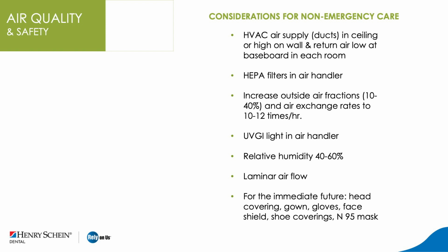We also want to have a relative humidity established in our office somewhere between 40 and 60%. I mean, you're going to find it's much more comfortable the closer it is to 40 rather than 60. And the way that most of us are going to accomplish this in our office is through portable humidifiers that are strategically placed throughout the office to maintain that humidity.